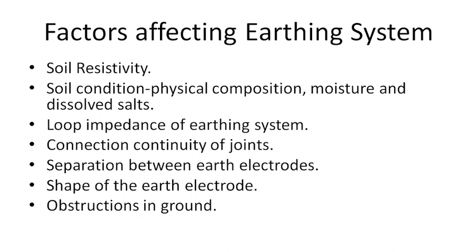There are several factors. In fact, first one is the soil resistivity. If the soil resistivity is more, the earth resistance will be more, and therefore it will cause hindrance in the current which is flowing to the earth.